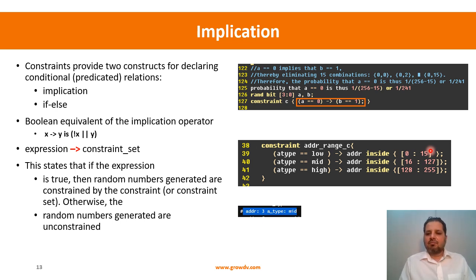So you can put a solve before construct if you want to impose that relationship. But when such a relationship is not defined, the constraint solver can solve these two variables independently and must ensure that this Boolean expression equivalent that I have defined must hold true for the implication operator. But in just a layman's view, if you want to remember without worrying about the theory that I explained, always remember that it goes from left to right, not from right to left.